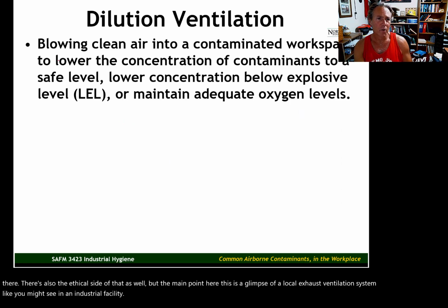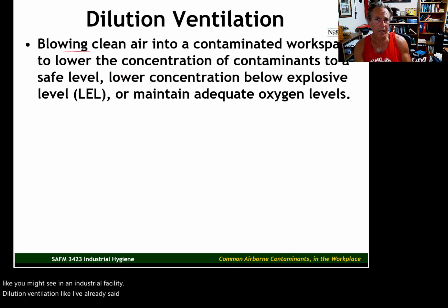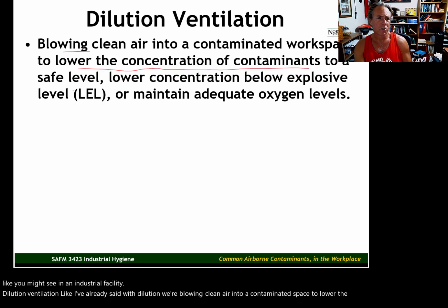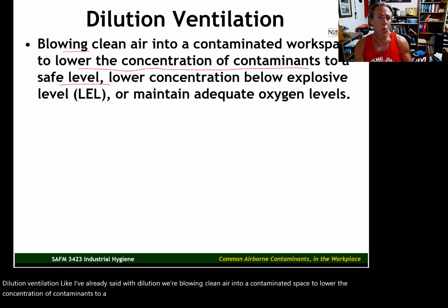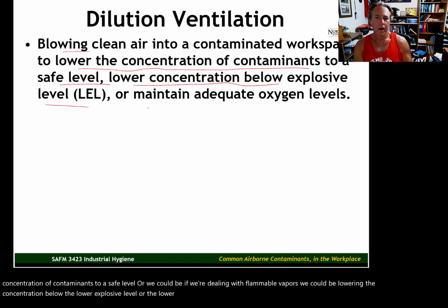Dilution ventilation. Like I've already said, with dilution, we're blowing clean air into a contaminated space to lower the concentration of contaminants to a safe level. Or, if we're dealing with flammable vapors, we could be lowering the concentration below the lower explosive level or the lower flammability limit.